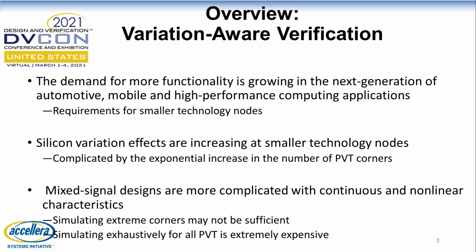Traditionally, it is performed via simulating extreme cases, which are worst-case corners. This is attractive in verifying designs that are characterized by ample margins, such as digital designs, where failures are mostly noticeable in those corner cases, and the cost is reasonable due to the limited number of corners.